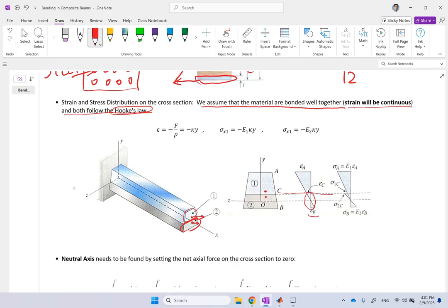And then when it goes to the weaker region, you're going to have bigger strains. But when you transition from the weak to the strong over this boundary, there is continuity. There is no abrupt change. So the profile of strain is a line, not like when you come to here, then you have a jump and then you go back and then you have the rest of it.